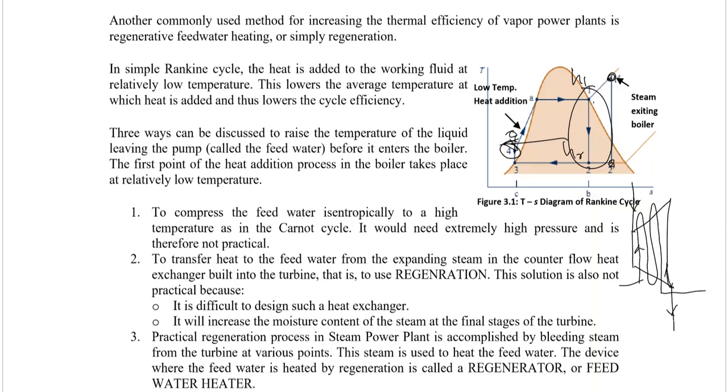First, it is difficult to design such a heat exchanger, which we would actually be building around the turbine periphery. So that would definitely be a little bit difficult. And even if we do so, there would be an increase in the moisture content of the steam at the final stage of the turbine. So already, if it is expanding from state one, enthalpy H1, to H2, and we